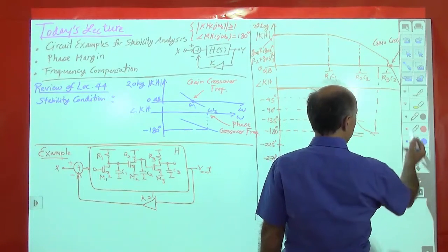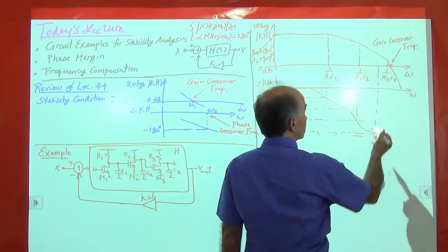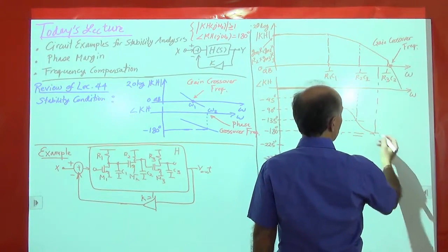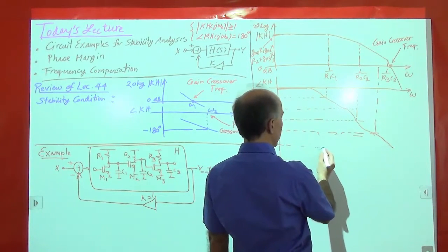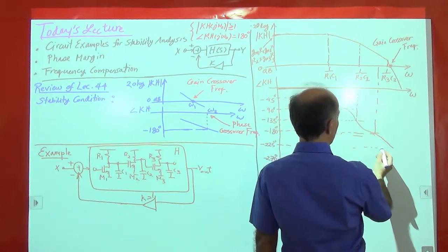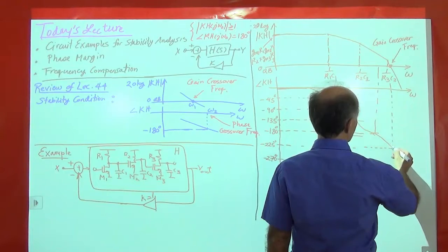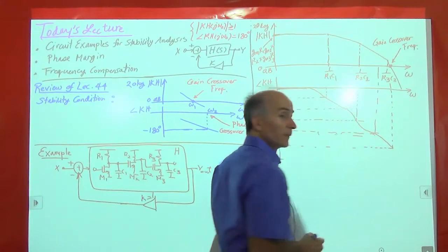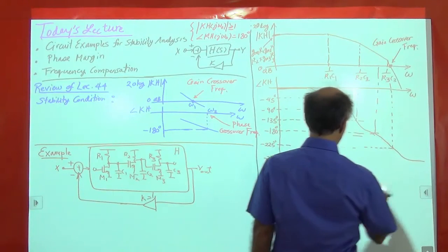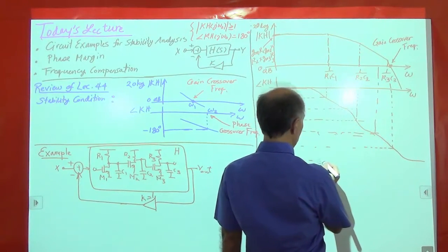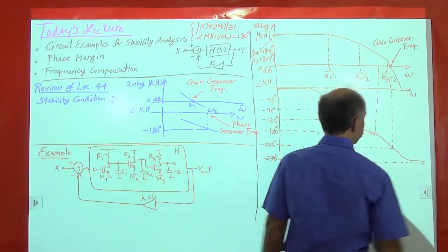And we have, let's go back to these colors here. So again, we begin to feel it at 1/10 of the frequency. We are at minus 225 at the third pole frequency right here. Right? And then eventually we asymptotically approach minus 270 degrees because each pole contributes minus 90 degrees.